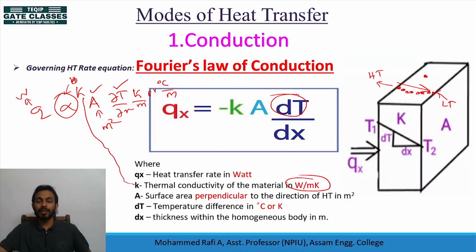Here I am talking about the temperature difference, so it can be either in degree Celsius or in Kelvin. That doesn't make any difference, because whenever you say a 5 degree Celsius temperature difference, whether it is 5 degree Celsius or 5 Kelvin, both have the same physical meaning. Right? Whenever you are talking about the temperature difference, whether it is in Kelvin or degree Celsius doesn't matter. But in radiative heat transfer, there will be some difference. I will discuss that in detail at that point of time.